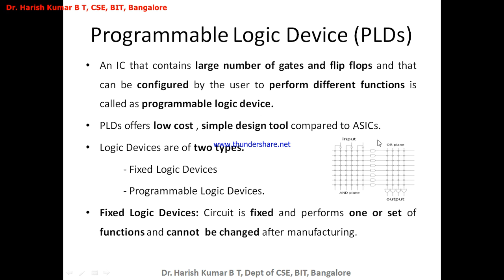I have a small picture here. So this is the input, this is the AND plane logic, and similarly the OR plane logic is connected, and these are all the switches. By switching on or switching off the circuits, you can get the output for any function. Now PLDs are low cost and have simple design tools compared to application specific integrated circuits.